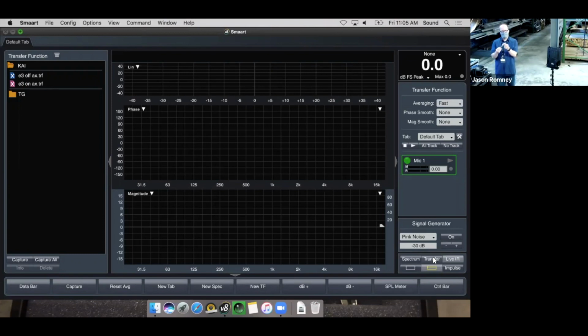This, however, will be very flat, even up to high frequencies, because it'll be omnidirectional. And remember, it's the omnidirectional that makes it flat. Okay, so that's kind of what you're looking for in an analysis microphone. The other thing is, depending on how much money you spend on the analysis microphone, of course, it will never be perfectly flat, no matter how much money you spend on it. But the more money you spend on it, the more likely the manufacturer is going to take the time to figure out the imperfections within each microphone.